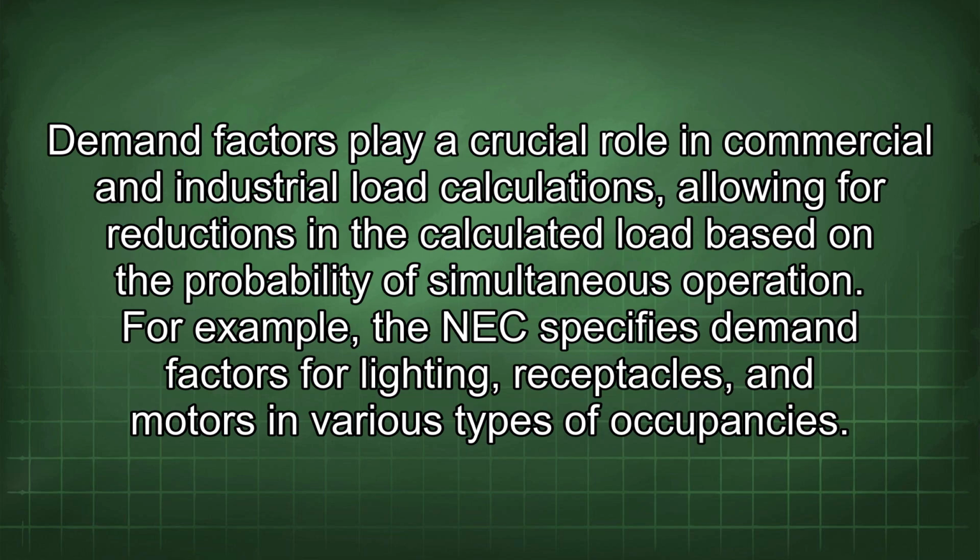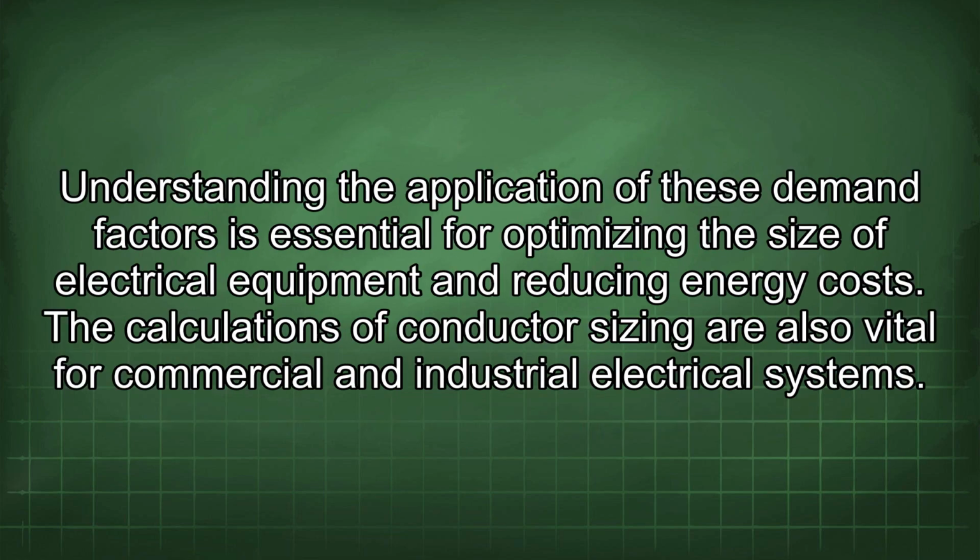For example, the NEC specifies demand factors for lighting, receptacles, and motors in various types of occupancies. Understanding the application of these demand factors is essential for optimizing the size of electrical equipment and reducing energy costs.